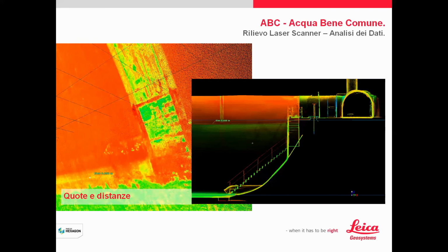And I want to spend two words again about reflectivity, because by reflectivity it's possible to see differences of color on the same surface. And if on this surface something is marked by numbers, if you know here 700, that means that this is the line of 7 meters. So I have created a new UCS where my blue line here was put at 7 meters.